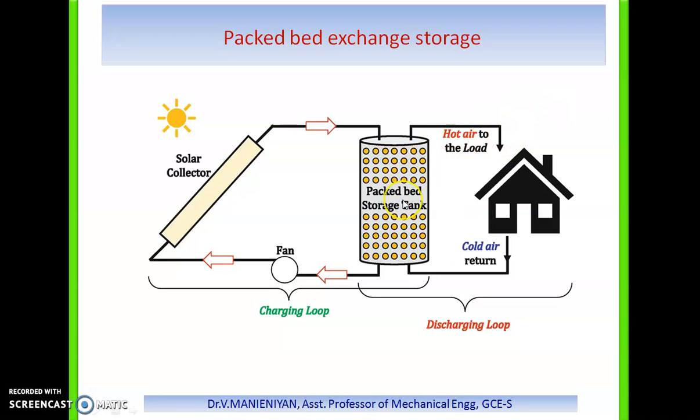If you use rock, some of the advantages are: rock is more easily contained than water. Rock acts as its own heat exchanger, which reduces the total system cost. The heat transfer coefficient between the air and solid is high. The cost of the storage material is low. The conductivity of the bed is low when air is not present. Some of the packed bed system arrangement is shown here.